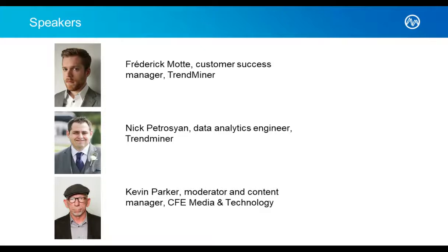What tools exist for cleaning data? For example, to remove data from unit processes when they are temporarily shut down, so that you don't have extraneous data involved. Right, that's a great question because we use this functionality in TrendMiner a lot, and we simply call it filters. So in TrendMiner, it's really easy to set up conditional filters that will basically filter out or remove data from a data set based on some criteria that you set up.